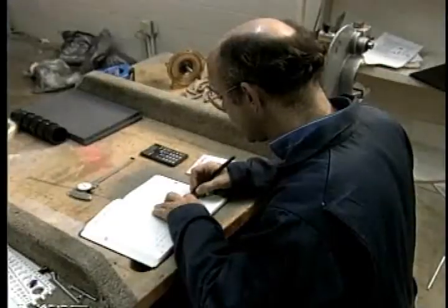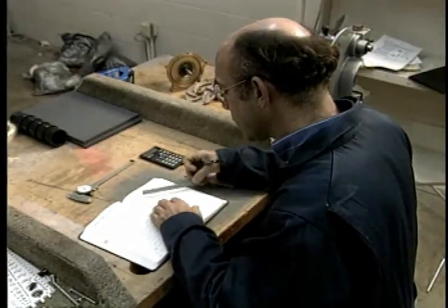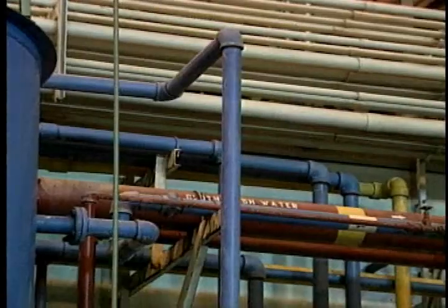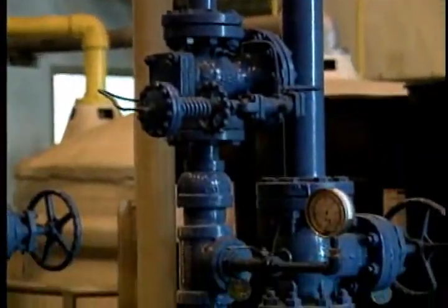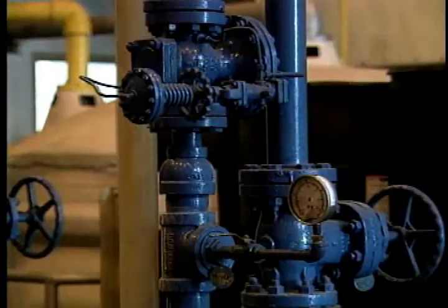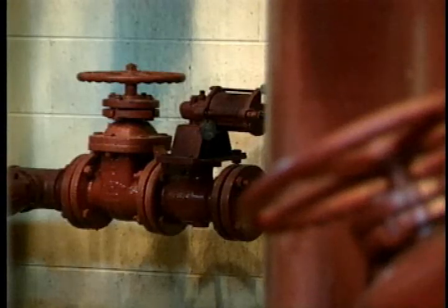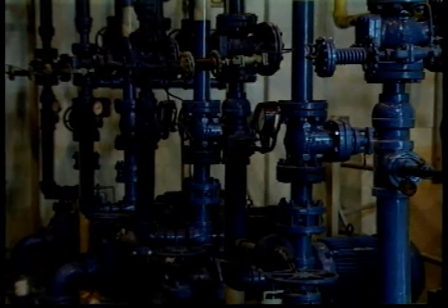To calculate the total friction head, just add up the individual friction heads of all the piping, all the fittings, and all the valves. The important thing to understand about friction head is that every foot of piping, every fitting, and every valve adds to the work the pump has to do. If old piping has rust or scale, or if a valve somewhere is stuck partway closed, pumps will have to work harder because the head is greater.